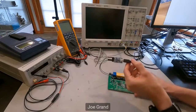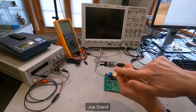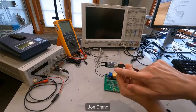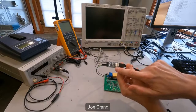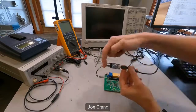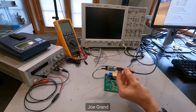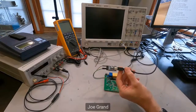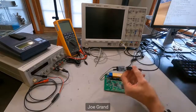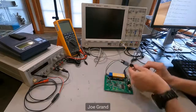Okay, so when I turn this thing on, it's probably going to be a little blurry, but if you look, you're going to see activity on the FTDI friend. It's blinking green on one of the LED indicators, which means it's receiving data from the target and sending that over the system. If I was hitting keys back, you would see it on the red LED coming up. So even without having a terminal program, you can still visually identify, okay, data is being sent.